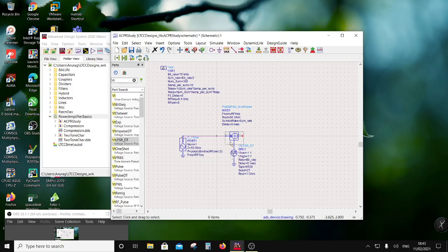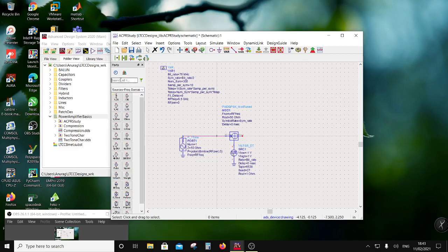So I'm all set here to put in random number of bits here, and these bits are going to be bunched up into 2 bits per symbol, and then they are going to do a differential QPSK out here, right? So then what I can do here is I can filter it. So I'll show you why I put a filter.